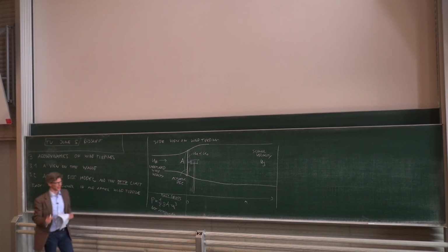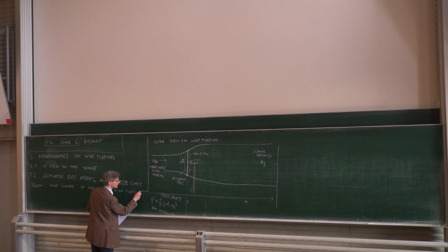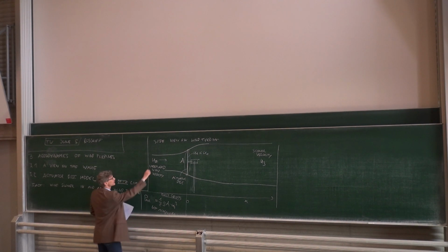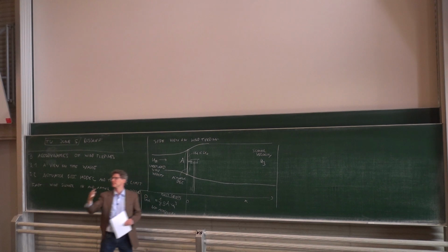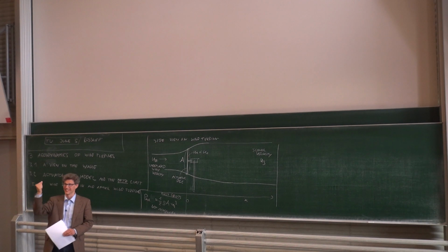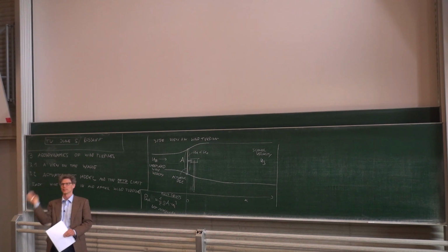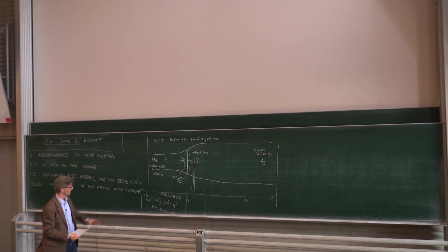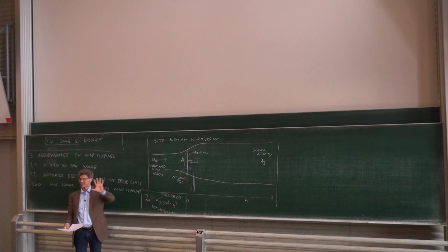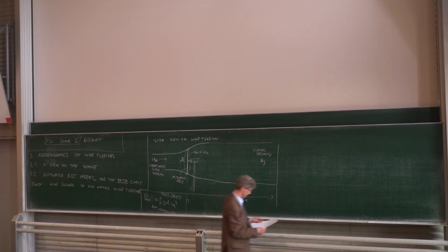But actually it still has a name, and we could call it the power in the air. That is in principle the power in the air that would flow through the actuator disk if there were no actuator disk. So if you would just place a ring, like a hula hoop, into the airfield and watch the air flowing through it, then you would have this power. But because you actually need to slow down the air, you will not get that power, unfortunately. And then there's this factor that is due to Betz, which we will derive.